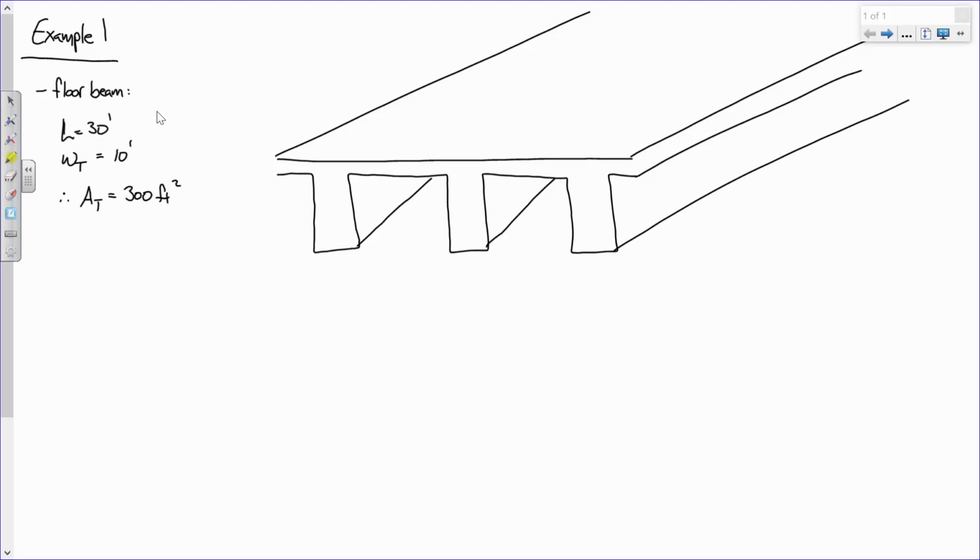Like that. Okay. Now, if I remember correctly, this dimension from our floor system is going to be 10 feet, right? Because that's how far the floor beams are spaced out, right? And what you told me was the tributary width of this system was just that, it was 10 feet. But remember, this floor system is subjected to an applied load.